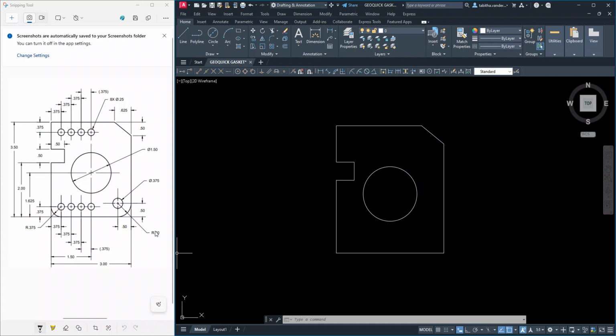But the most reliable measurement is that I see that this fillet has a radius of 0.5. Fillets are usually defined by a radius. And I can tell because the little arrow for this dimension is pointing to this circle right here. That is what is being defined, and this arrow starts right here, meaning that 0.5 would measure from here to here, getting the radius of this fillet.